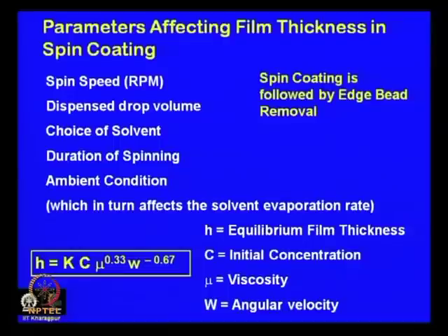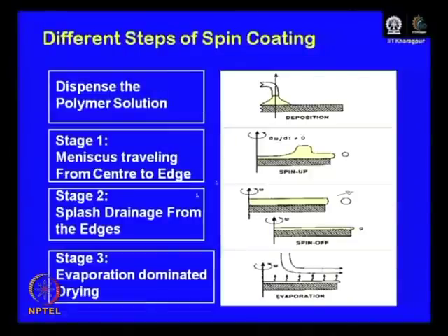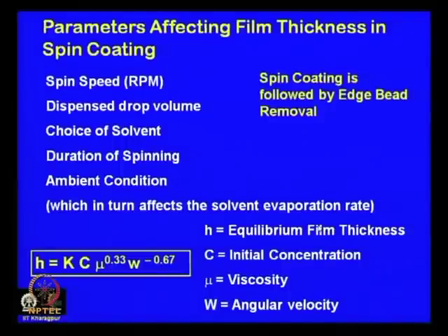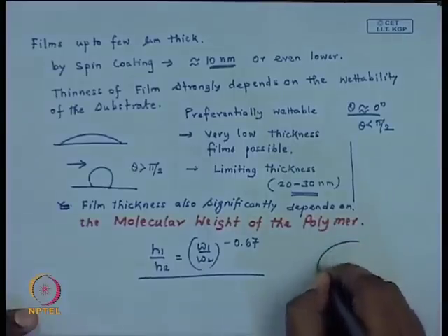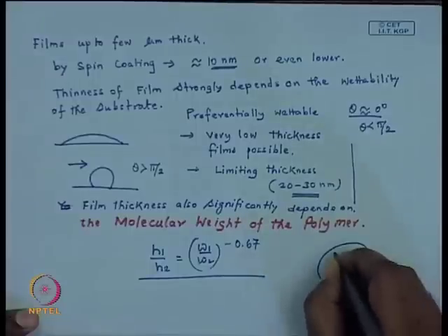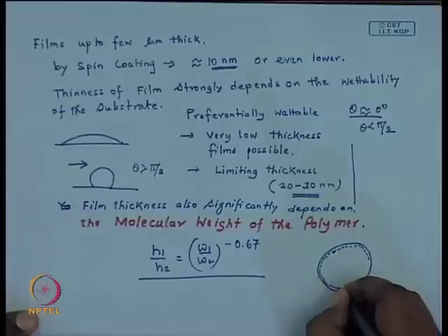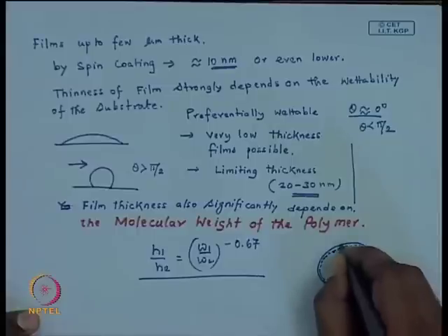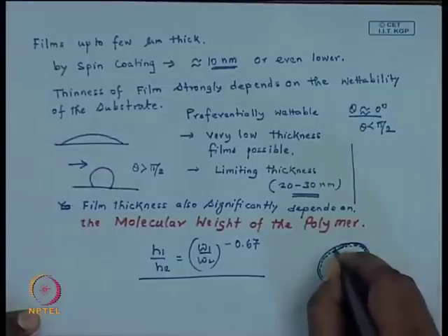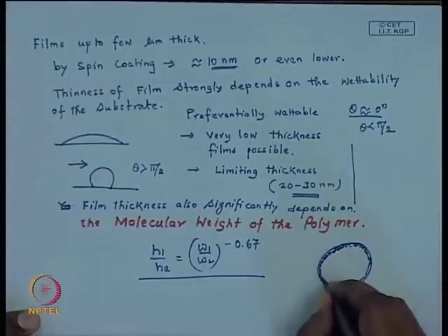Now, we had some discussion on the technique of spin coating. Let us come back to photolithography. Another aspect of spin coating is the splashing from the edges, and this splashing often results in some sort of inhomogeneity or higher thickness, or formation of globules or isolated patches along the periphery of the edge.